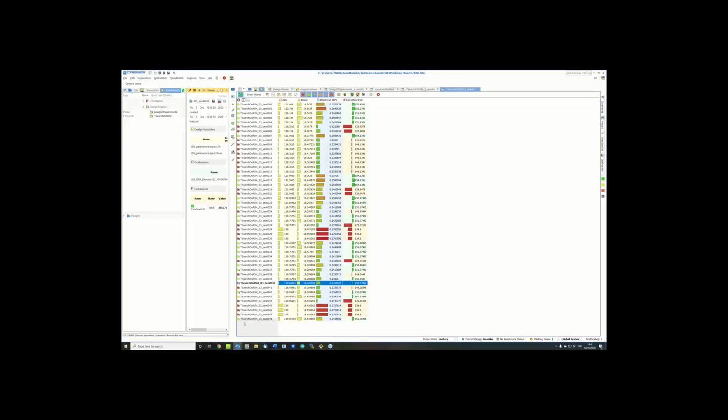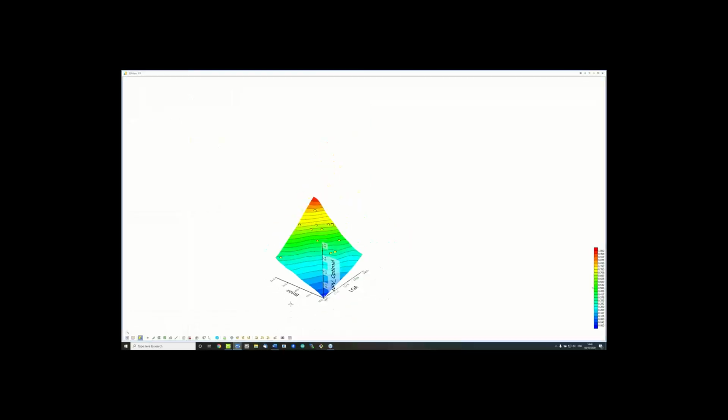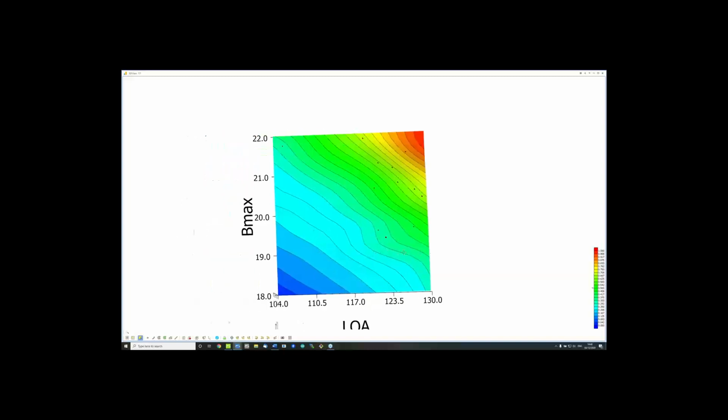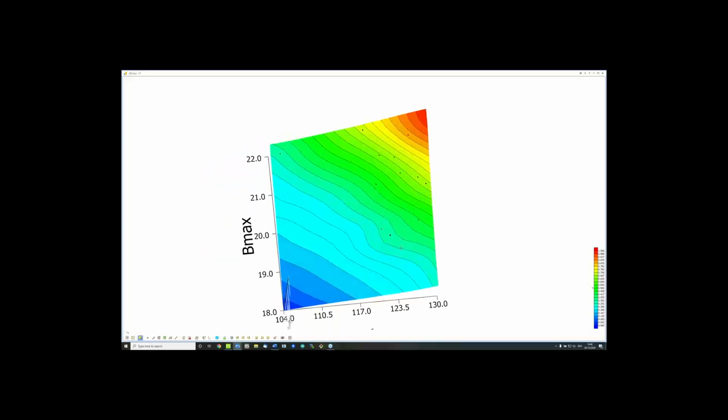And obviously, if we look back at those models here, there's also an obvious reason for this kind of behavior. If we take a closer look, we can find that there's only feasible designs above a certain threshold of beam. And that is actually the beam that allows to exactly fit 7 lanes of cars next to each other on this ferry. And that seems to be the minimum number of lanes that we need to fit 130 cars.